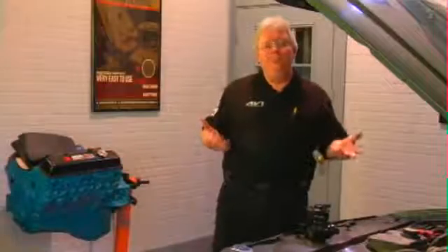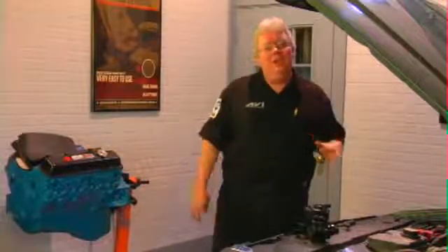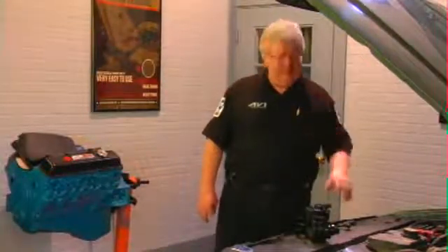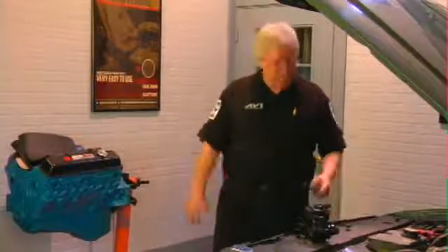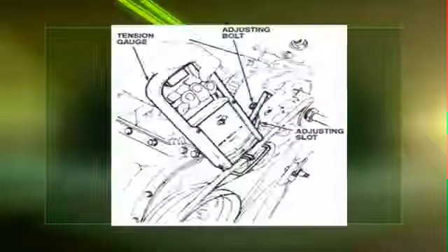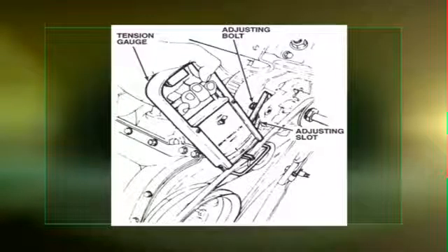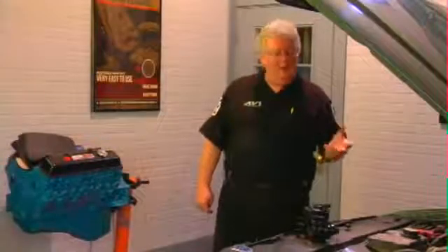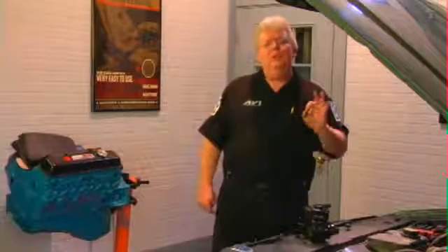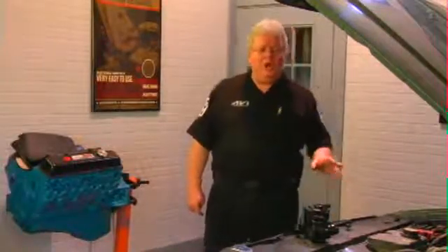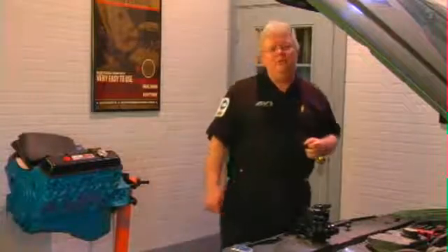Well, most V belts have gone the way of the classic car, but the multi-V serpentine belts are here to stay. In fact, they're evolving very much as well. As we look at the proper tool in this illustration, a belt tension gauge, if you've updated your toolbox for the multi-V serpentine belt, it's not a problem. But if you're going off of the old deflection, we need to know a little bit about how to do that. So let's take a look on the car using a simple tape measure.